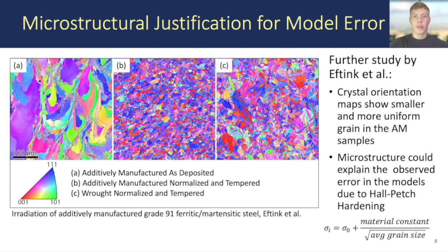These microstructural differences appear to explain the hardening observed in the isostress and isostrain models. Hall-Petch hardening, which increases yield strength as grain size decreases in the additively manufactured samples, is the most likely contributor to this effect. Considering these differences in microstructure, future work may be able to use isostress and isostrain models for rough estimates and quick calculations before using more time-consuming models.